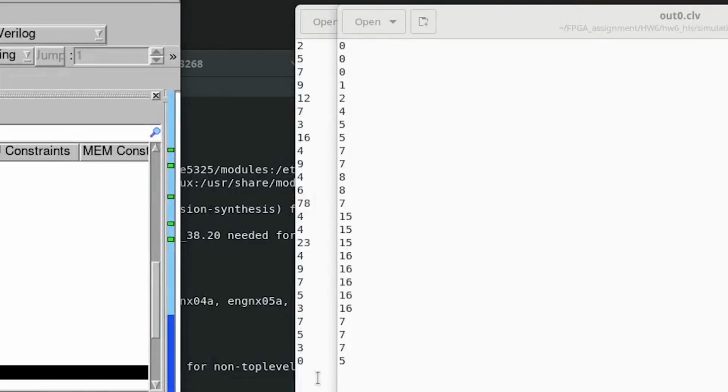This leads to a lag in the system, where it will take an extra cycle to generate the output. So here we can see an offset of one cycle. To accommodate for that offset in our input, our final value will be 0. Initially in the software simulation, we just had two zeros, but here we'll be having three zeros, where the first zero is just an offset zero, to accommodate for the simulator to perform evaluation between golden data and the generated data.